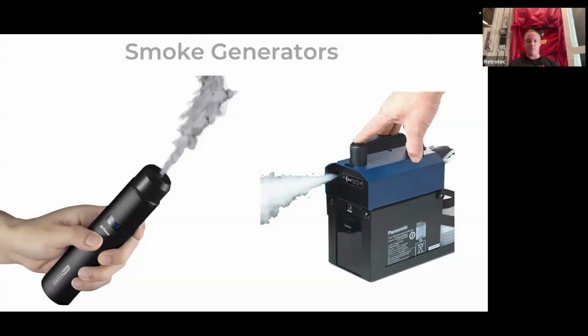This is also great for really seeing where all the failures are in a spray foamed attic. If they encapsulated an attic with spray foam, you can really fill it up, put pressure behind it with your blower door, and have somebody outside who can see where it's failing. A lot of times it's the soffit. That's what we see a lot, but it can fail in other places too.